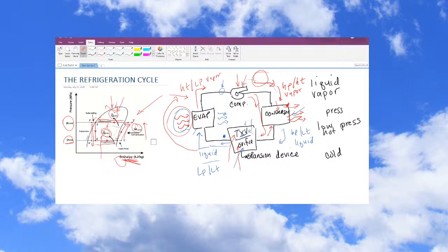When you're controlling boost and valve timing, a drive-by-wire throttle body, and interfacing with the body control module, and you have CAN bus communications with your ABS system and vehicle damage control systems and all that kind of stuff, typically 16-bit ECMs don't carry enough oomph to do all those parallel calculations and communications. Really interested if that was the EcoBoost as well.